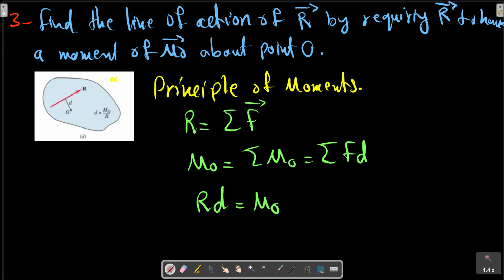The first two of these equations reduce a given system of forces to a force-couple system at an arbitrarily chosen but convenient point O. The last equation specifies the distance d from point O to the line of action of the resultant R, and states that the moment of the resultant force about any point O equals the sum of moments of the original forces of the system about the same point. This extends a well-known theorem to the case of a non-concurrent force system. We call this extension the principle of moments.